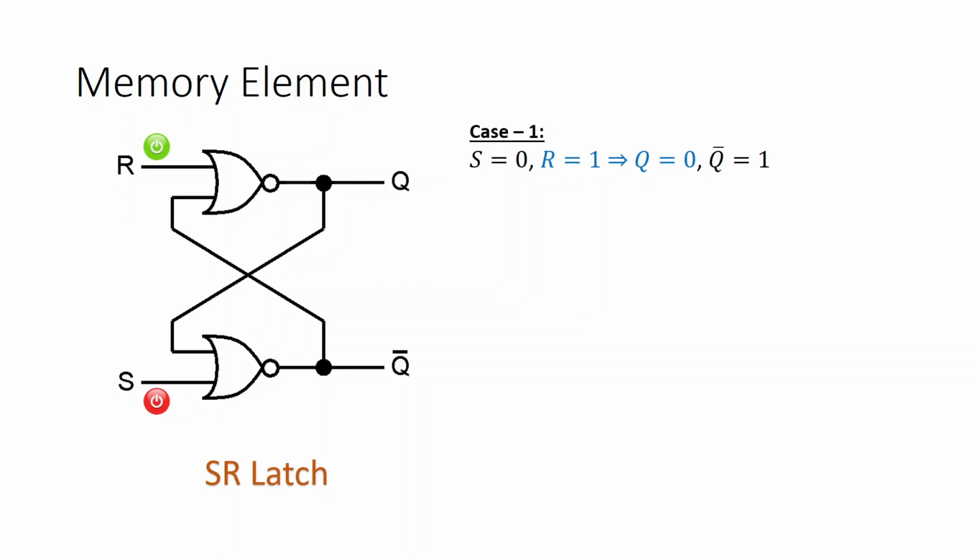Now, we have already designated the outputs as Q and Q bar, and you might tend to suppose that there is no NOT gate connection between them, but why are we writing Q and Q bar? Is it because they are always giving complementary outputs, that is when one is 0 another would be 1, and when one is 1 another would be 0, is it like that? So, the answer is not exactly so.